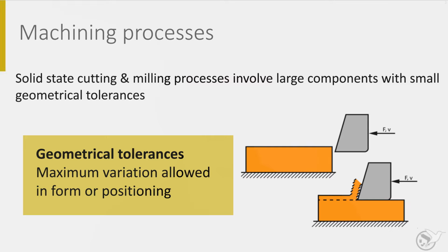With chip removing processes, chips or tiny bits of material are cut from the block, plate or sheet. This chipping is based on plastic deformation. Actually, the material is pushed away by high local forces. The plastic deformation and the high forces generate heat and tool wear. Therefore, processes like milling and drilling apply cutting fluids, whose purpose is to reduce the temperature, to reduce the wear by lubrication and to remove the chips.